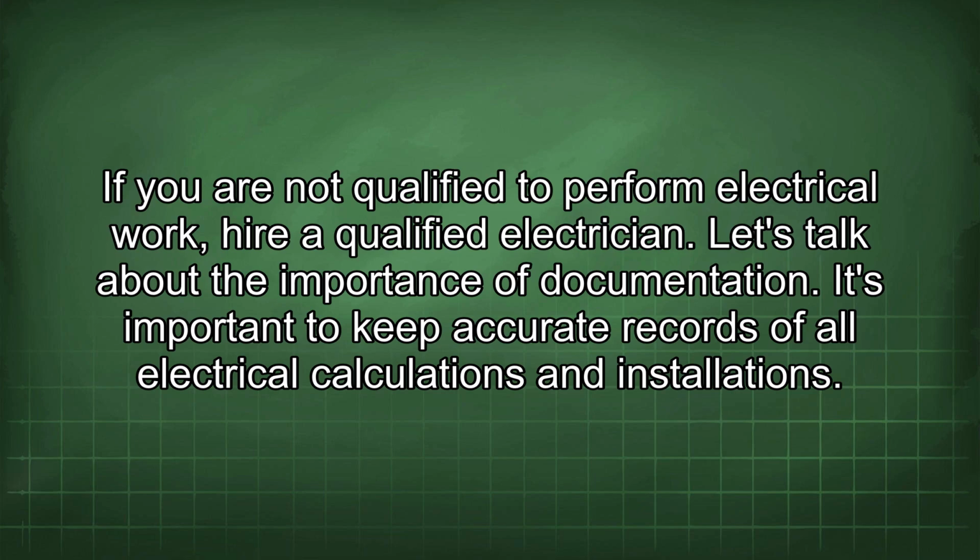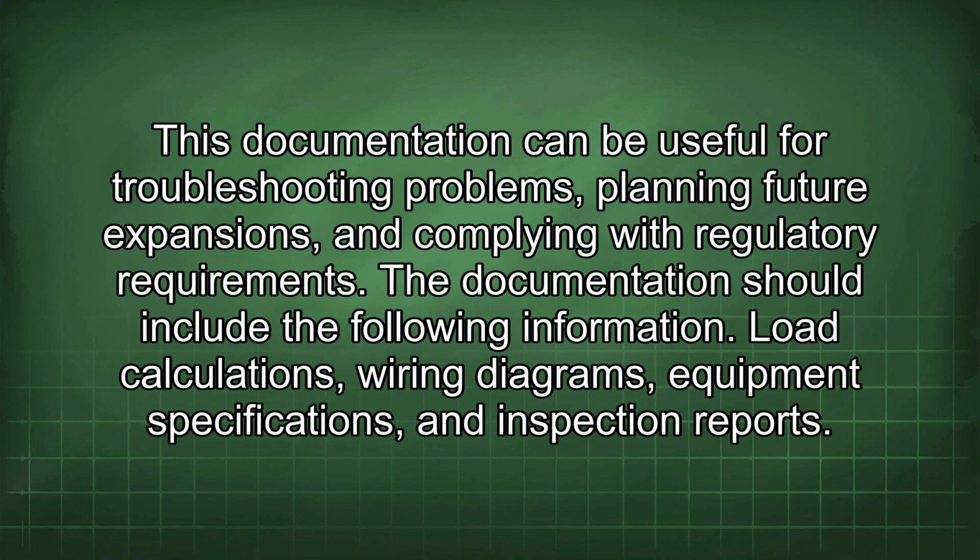Let's talk about the importance of documentation. It's important to keep accurate records of all electrical calculations and installations. This documentation can be useful for troubleshooting problems, planning future expansions, and complying with regulatory requirements. The documentation should include the following information: load calculations, wiring diagrams, equipment specifications, and inspection reports.